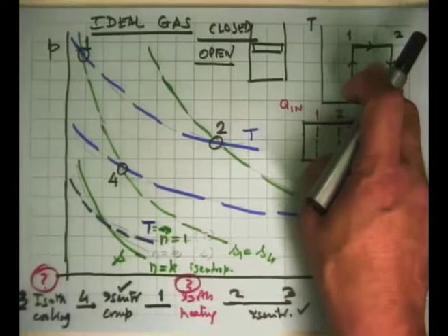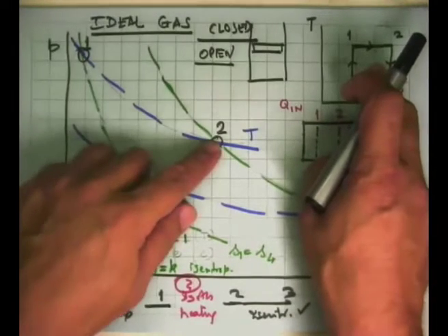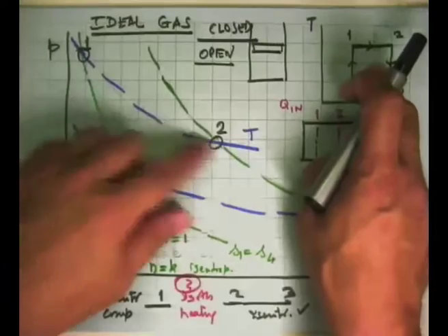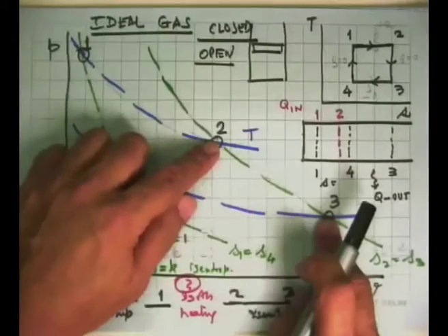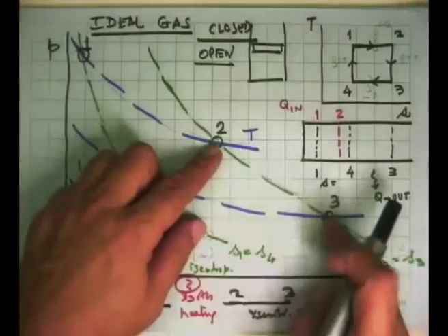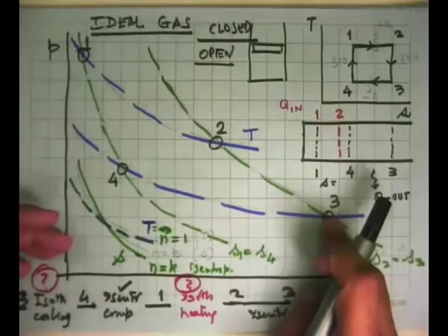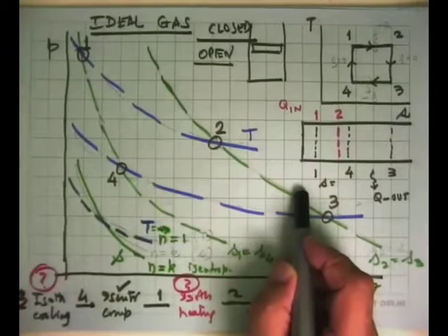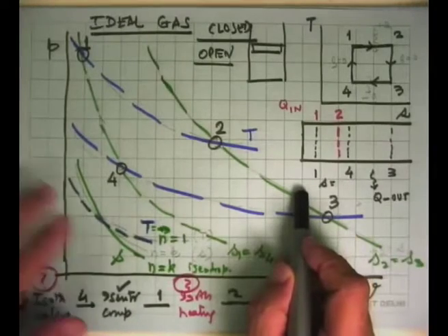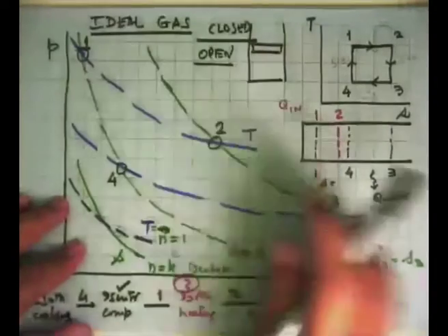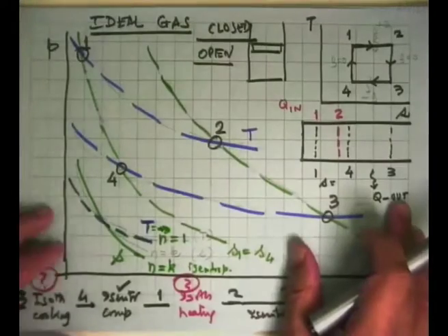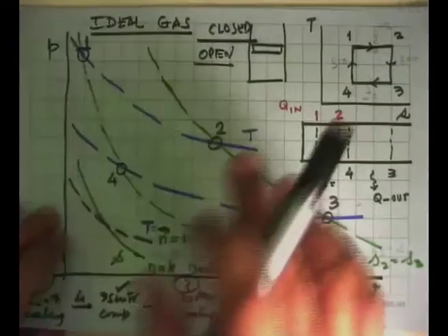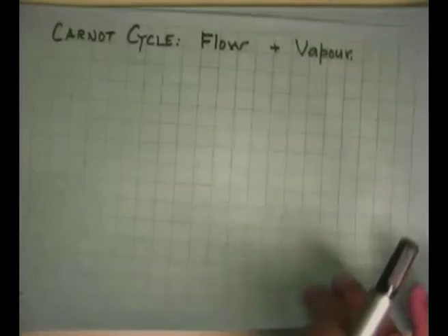The practical turbine, I said, what we can make is an isentropic turbine. That's the best we can do. This is again not possible. The last part is an isentropic turbine. We can do that and get close to it. So even in an open system, what we are seeing is we need 2 compressors and 2 turbines, 2 adiabatic, 2 with heat transfer. The 2 heat transfer ones are not possible. So again, the Carnot cycle as an ideal gas cycle, we cannot come close to it. This is the problem with the practical realization of the gas-based Carnot cycle. Okay, so that is what happens to the Carnot cycle with the gas.